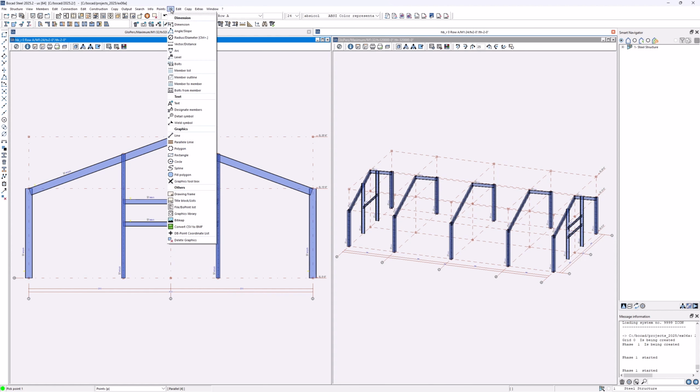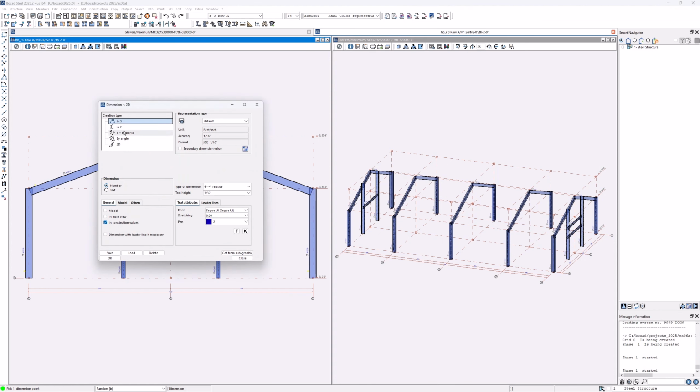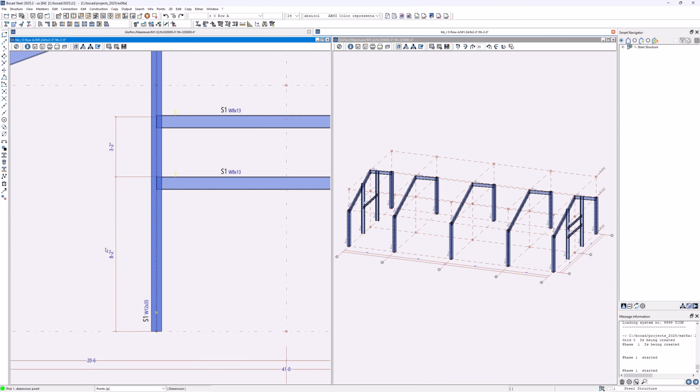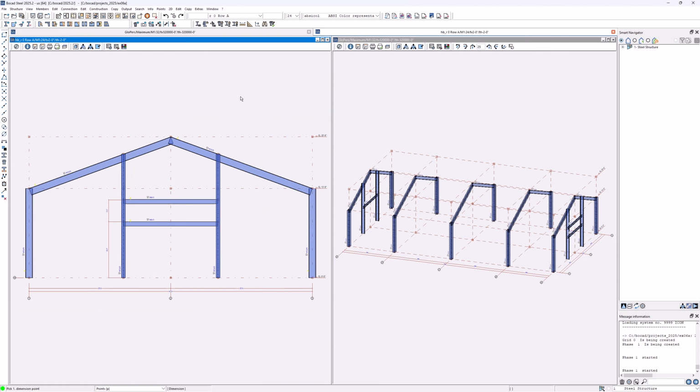And if I want some visual checking, I can definitely add some dimensions in there. Y value relative 1, 2, 3 locations. Drag the dimension over here. If you think, well, the text is a bit small, of course, feel free to zoom in. That's one thing. But as we already know in the meantime, we could also change the scale a little bit.